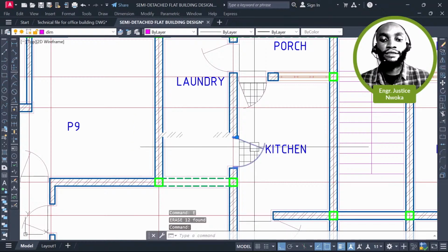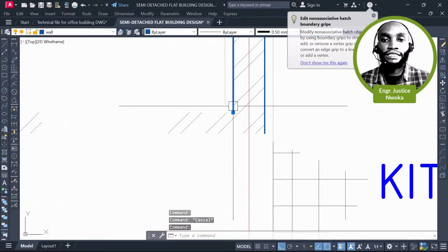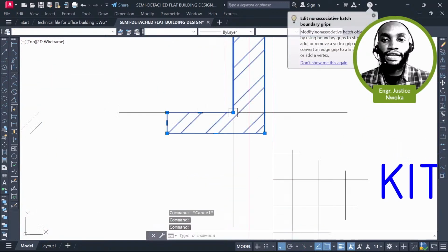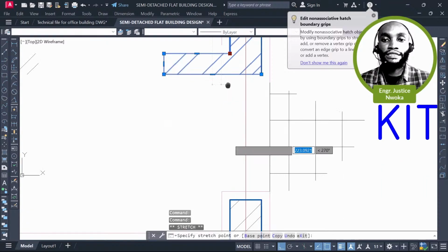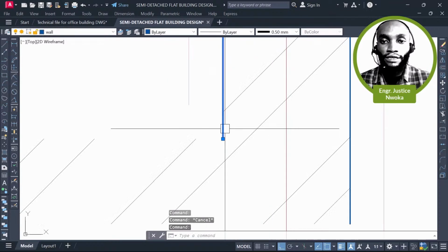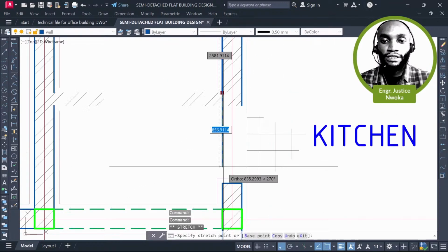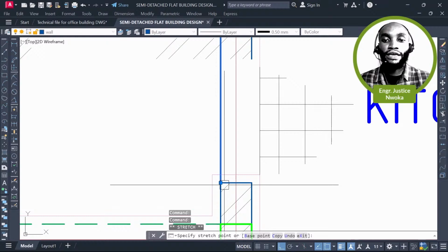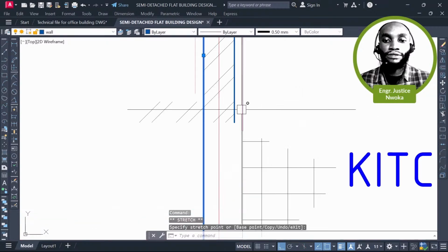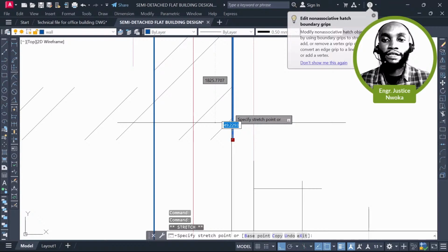And then try to extend this line here, extend this line out, sorry for that, just click on this, not the hash but the line, and then extend this out here. That's now a beam, how our beams are going to run. And again click on this and then click on this here and extend this out here, that's fine.